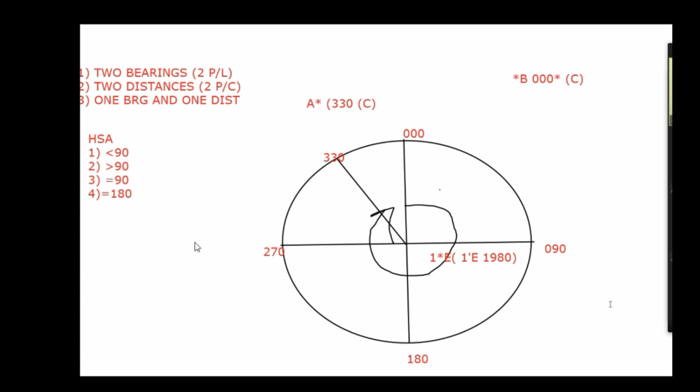Okay, compass course. And why is the deviation different for various ships? Because the size of each ship is different, and depending on the size, every ship itself is a magnet. Because every ship cuts the Earth's magnetic field, as you must have seen in your bridge equipment, the ship becomes a magnet. Depending on the steel structure, the magnetism effect will be more for larger vessels.